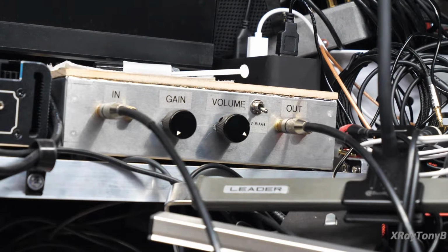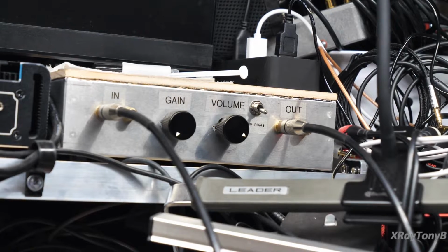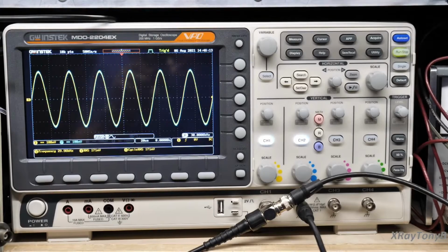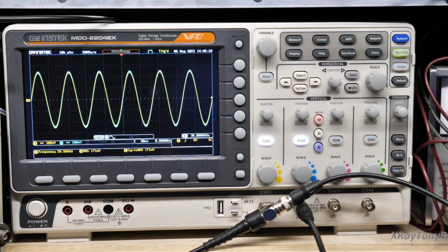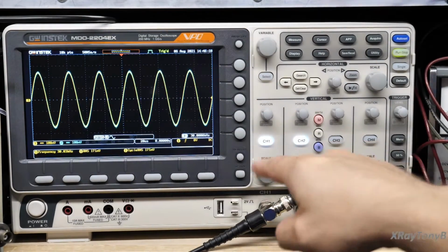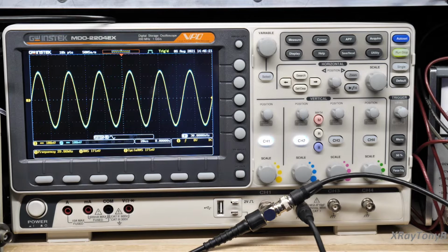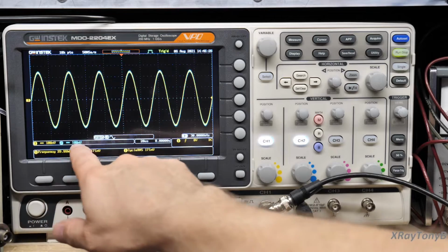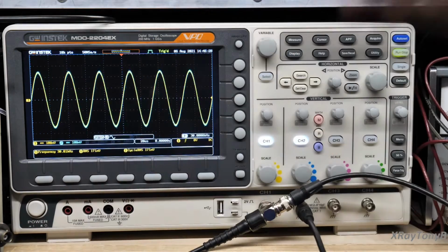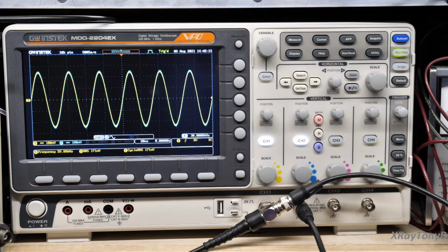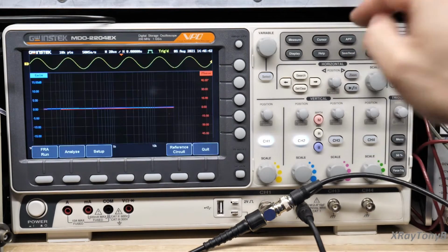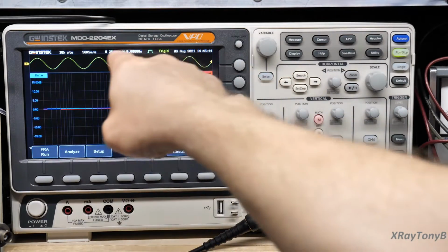And if I move over here, let me get you moved over here for a minute. You can see there's our input and output once again. So the amplifier, or this buffer preamp, actually has unity gain. In other words, you can see we're on the same scale for channel 1 and 2, and you can see they're falling right on top of one another. So the gain is unity gain. Whatever's at the input is the same amplitude as at the output. Okay, let's go back to our application for a second, and you can see it right there.